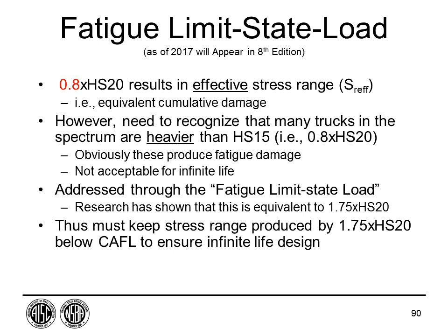Now today, as of the 8th edition, we had a ballot last year at AASHTO, the fatigue truck weight, I said it was 0.75. That was the original research that developed that. But there's been additional studies, additional weigh-in-motion studies, that have looked at the load spectrum in this country. And it's been creeping up, as you can imagine. So instead of 0.75 times the HS20, the vehicle is the HS20 times 0.8. Now you might think, well, that's not a big deal. And it's not a huge difference, but it's just trying to stay current, that things are changing.